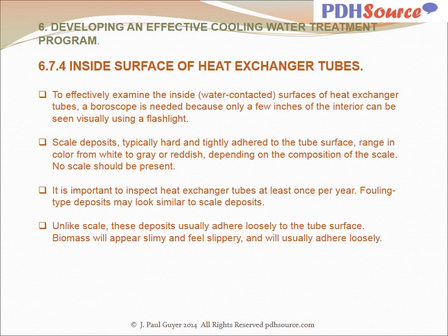Fouling type deposits may look similar to scale deposits. Unlike scale, these deposits usually adhere loosely to the tube surface. Biomass will appear slimy and feel slippery and will usually adhere loosely.